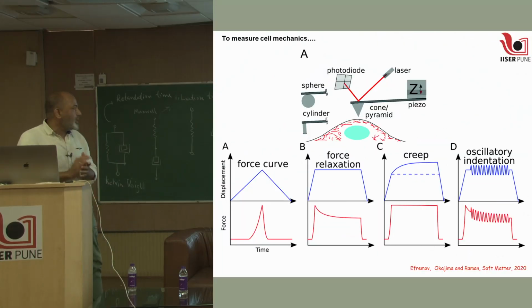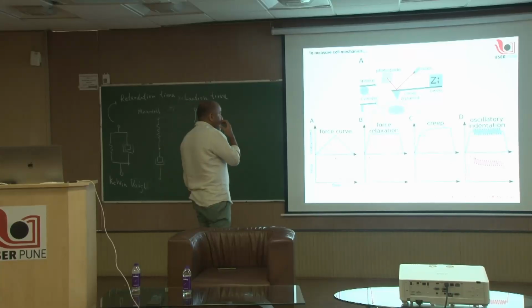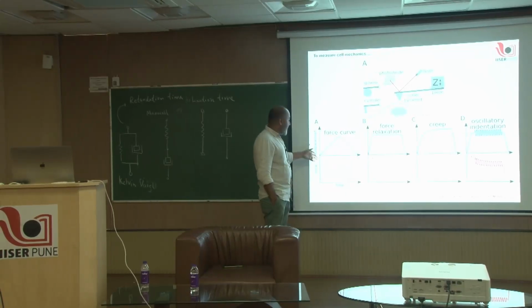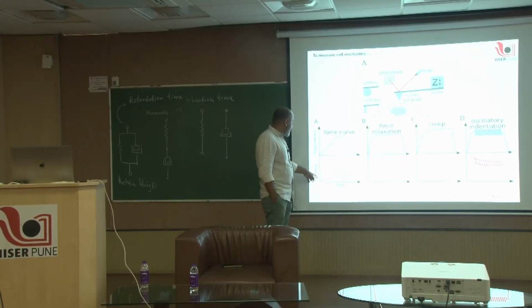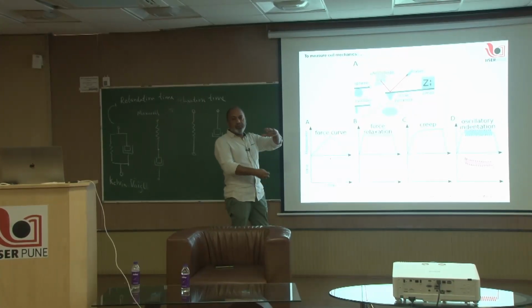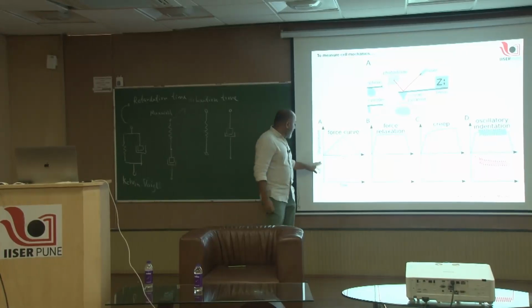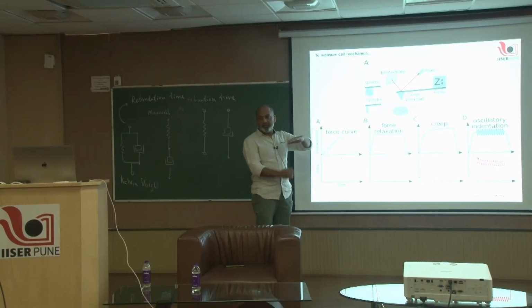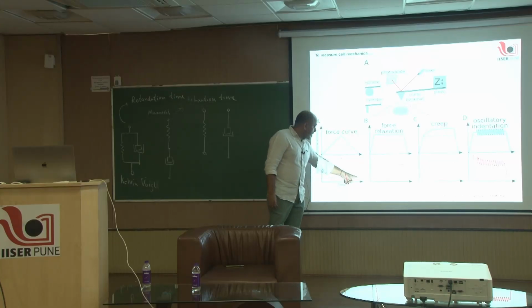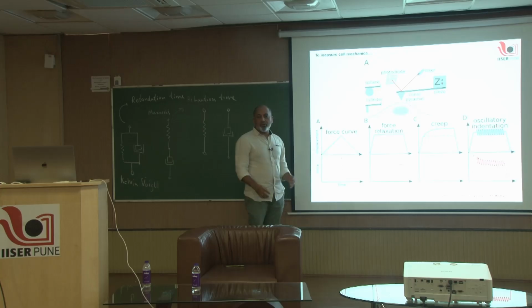In the case of AFM, one can do different kinds of experiments to get this exponent. The simplest protocol, which many of you have probably already done in your labs, is that we apply displacement to the cantilever. We come with the sample, press on the cantilever, and come back. This is a triangular displacement applied to the piezo. When there is no contact you do not have any force, and the force goes up and comes down to 0. This is one standard protocol, basically measuring a standard force curve.